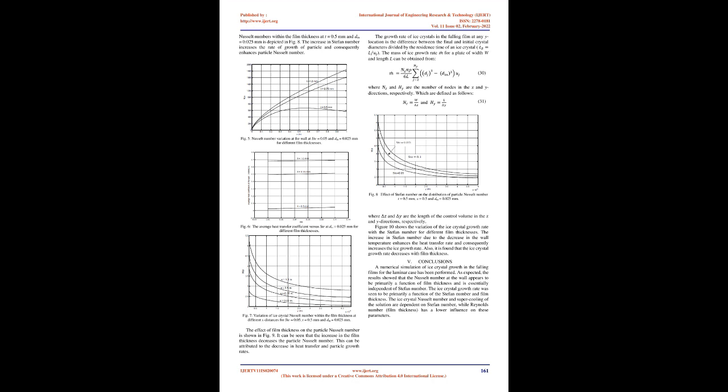As can be seen, the greatest concentrations are near the plate surface. This may be attributed to the fact that the mass transfer process from the solution to the surface of ice particles is more significant near the plate surface and increases in the streamwise direction, which is responsible for increasing the ice particle diameters, and hence, increasing the ice slurry concentration.